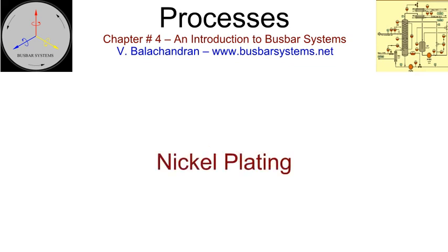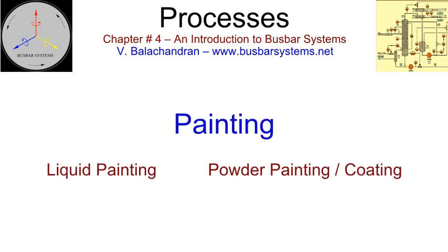Nickel plating. Nickel plating is cost-effective and provides a stable contact resistance. Nickel plating will make the surface hard. Its superior performance is attributed to lesser differential thermal expansion with respect to a substrate of copper and aluminium under current cycling. Painting. Painting of conductor and enclosure serves a dual purpose. It protects the surface from adverse environmental conditions. It increases the relative emissivity of the surface, thereby improving the heat-absorbing and dissipating capability of the coated surface.